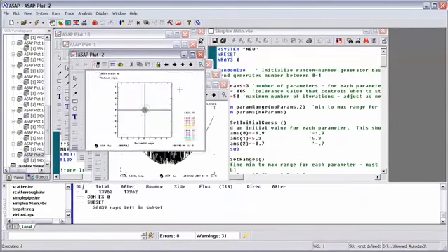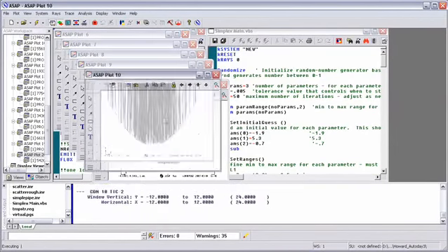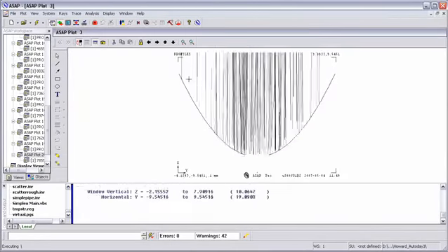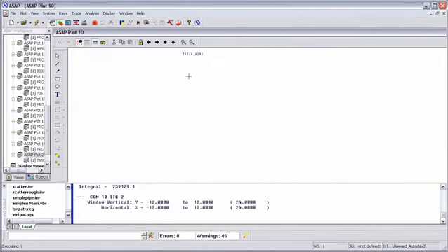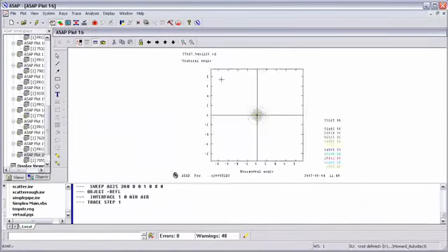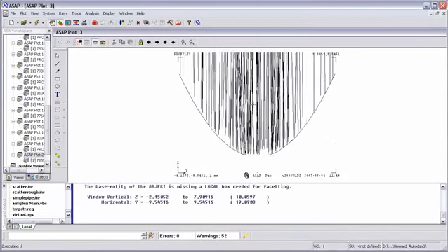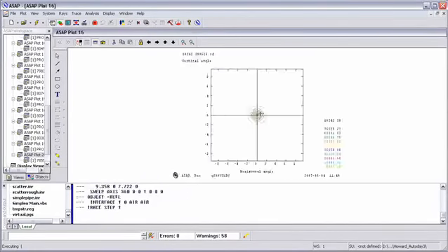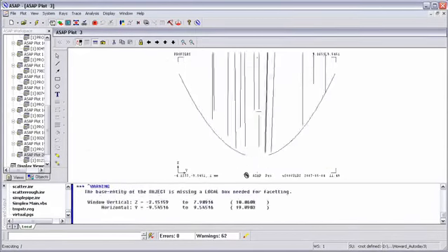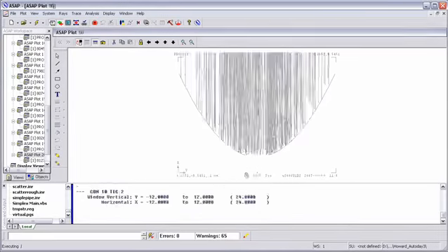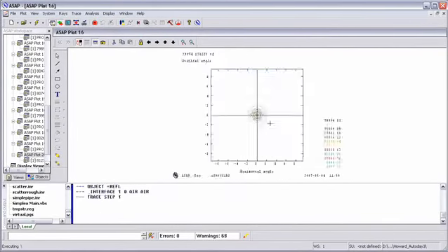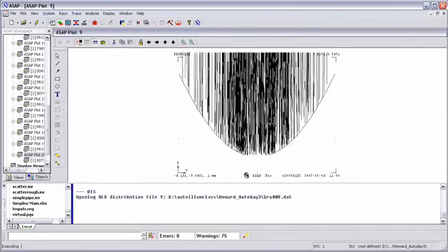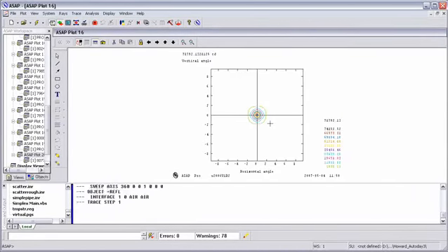And the ASAP is automatically running the simulations and changing the geometry each time in order to try and maximize the intensity at the center point. If you recall the first simulation of the component, right now we're seeing center values of around 80,000 candela. The first simulation of our component had center values of around 29,000. So the system's increased fourfold in performance automatically through the optimizer.